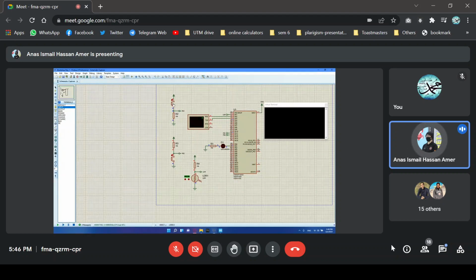If we press the button now, this should have a high value. The LDR decreases the resistance value the more you increase the light intensity. So it's an inverse relationship. If I press now, let's say it's 3796. If I increase the intensity by like 300 and then press again, it should decrease.